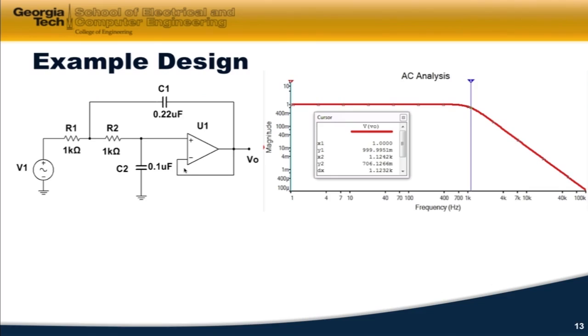And here you can see that I've set the gain equal to 1 by making this resistor a short circuit and the resistor that was here an open circuit. The simplest way of making the gain 1. Once this is a short circuit, the value of this resistor doesn't matter, but the best solution is to just leave it out because that makes the circuit a little less complicated.